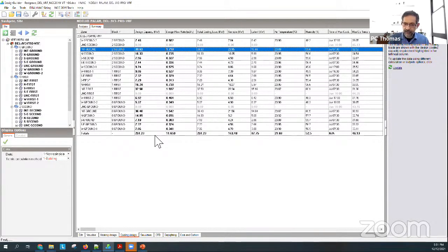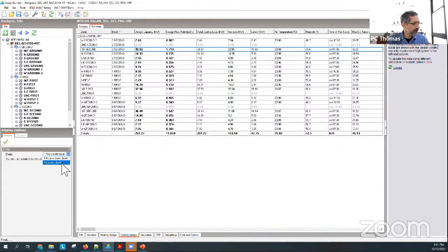You want to find out when the building peaks, when is the highest load when all the zones are at one time providing to the chiller. If you click this and say coincident, you can see it went down from 251 to 244. That difference is the diversity which you can put in your system. It's not a lot on this one. In some buildings, it can be quite big. And you really only need to size your outdoor unit or your chiller for this size.